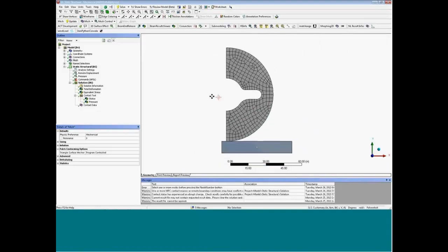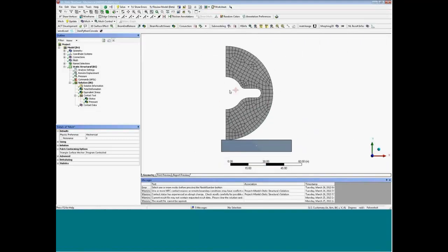Say your solution failed to converge because of some element distorted. Well, then you can look up where that element's located in the model. So, again, that's something that's available for GUI manipulation or accessing information out of the mechanical GUI. Let's look at another example.